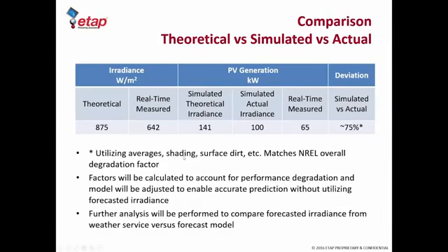Then we actually have shading differences. Depending upon the location of the structure with respect to surrounding buildings, shading is a factor. Now, in commercial spaces, that may or may not be controllable, but obviously if you're dealing with a solar farm, that is easily managed by just adjusting the spacing between the panels so that the shadow of one does not affect the other.